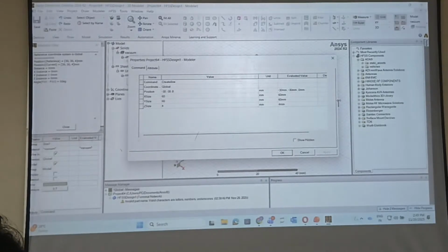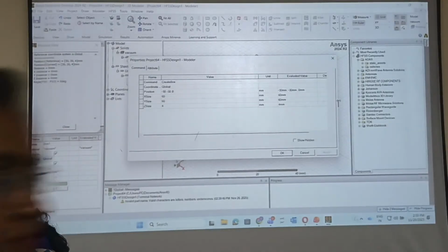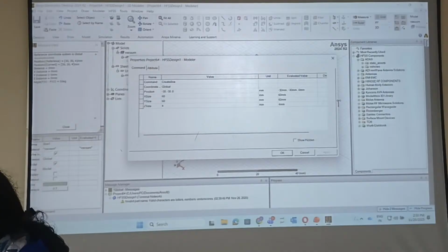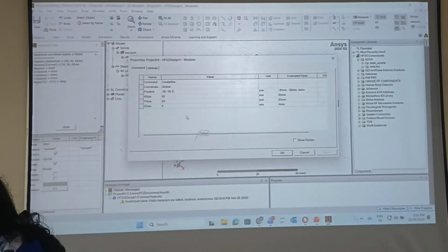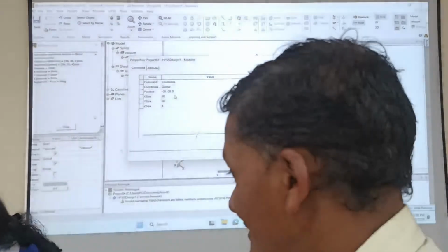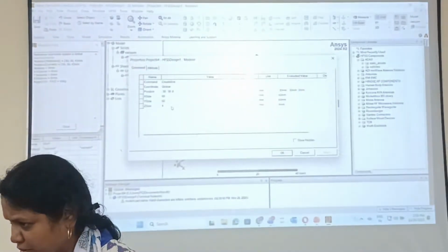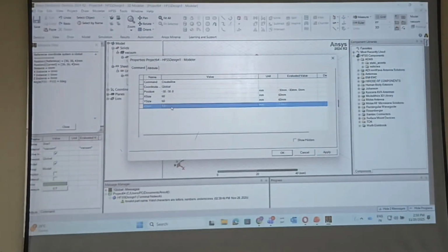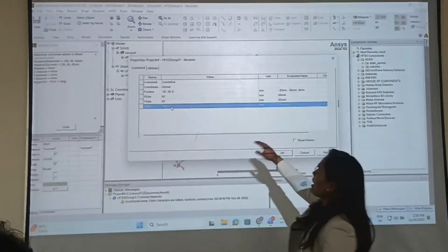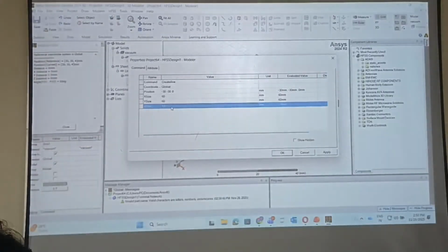1.6. Height of the substrate is 1.6. I didn't change anything. Wait, once again, I'll tell you the dimensions and then I'll apply. Your position should be -30, -30, 0. We are along the z-axis. Here x size is 60, y size 60, and z size you have to type 1.6 mm. Only change in Z itself. Positions are minus 30 comma minus 30 comma 0.